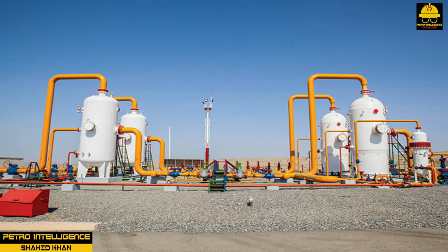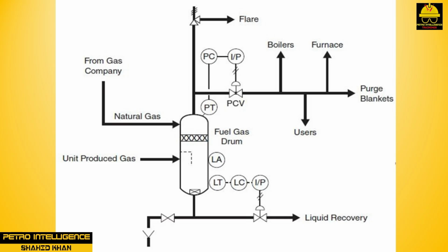Gas systems. Most industrial manufacturers purchase natural gas, NG, from suppliers. A high-pressure pipeline generally delivers gas to the plant. A pressure letdown station located near one of the plant entrances meters flows to the plant. The letdown station consists of multiple control valves, 2 of which are normally in service for backup. Additional valves are provided for peak loads such as unit startups.